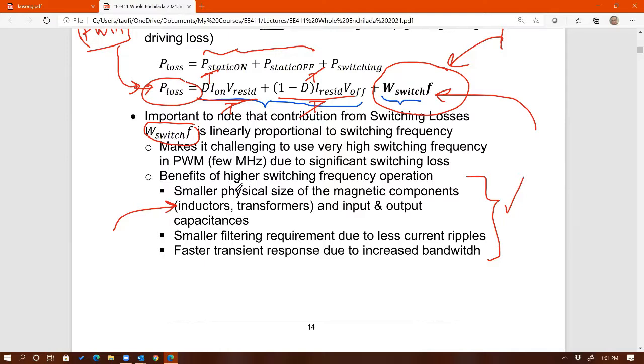So you're going to have to find a sweet spot when you're designing your magnetics, for example, or even other things, not just magnetics. At some point, your magnetic has to be operated at a certain frequency, beyond which hysteresis loss, or even the worse one, eddy current loss, becomes exponentially higher than at the previous frequency you used, as an example. So it's always a balance between these different factors for sizing the component.